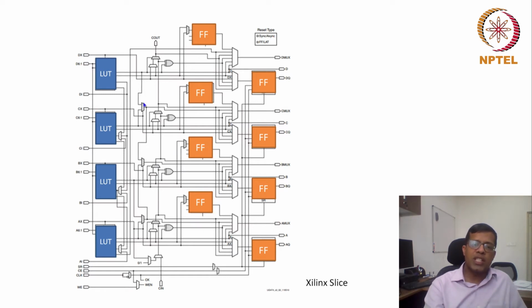This carry chain, which is hardwired logic, can help us boost the performance of at least addition, at the additional cost of hardware. One can argue that this additional hardware will go unutilized if this CLB is not implemented as an adder. That is true.